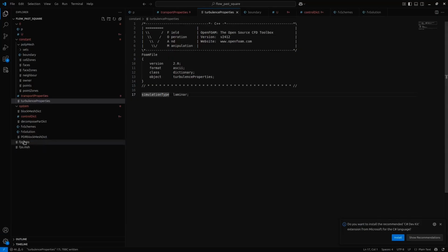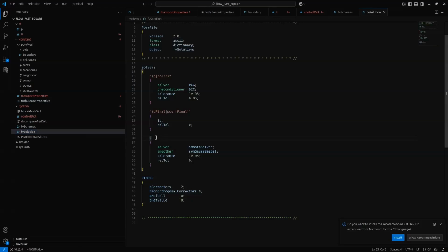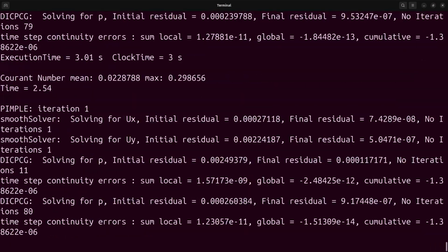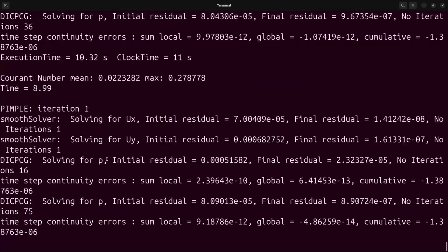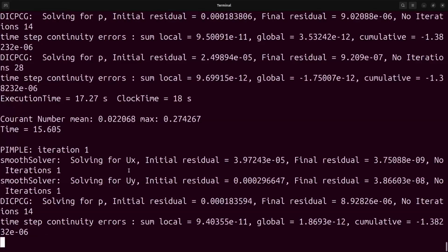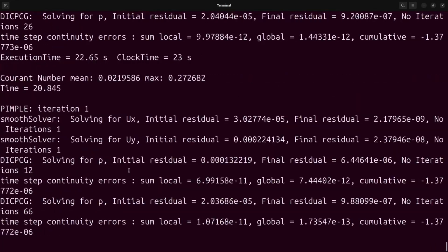Again, let's go back to the solver. Here you should have a UFinal as well. Let's add that. Make sure we are changing the right variable, and again rerun this. We can see that it is running fine. Let's run for some time and then we'll post process this. We'll just look at some kind of vortex shedding. Let's wait.